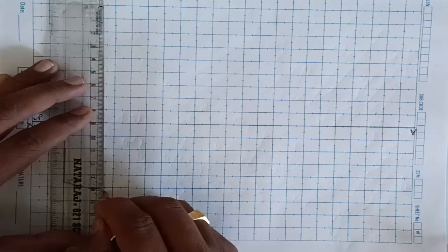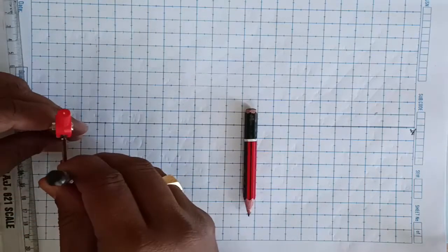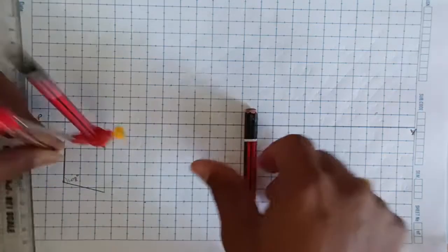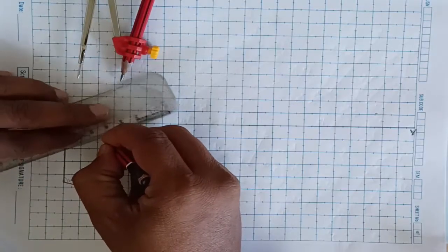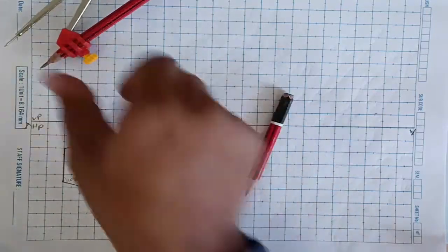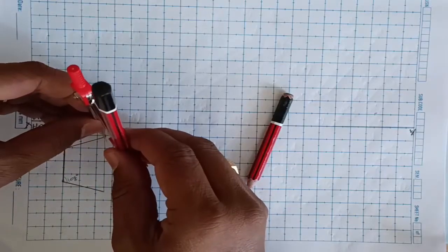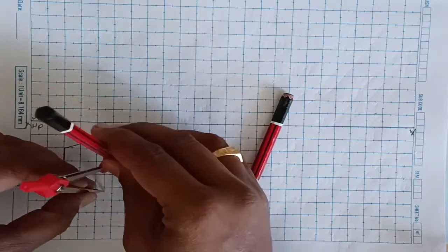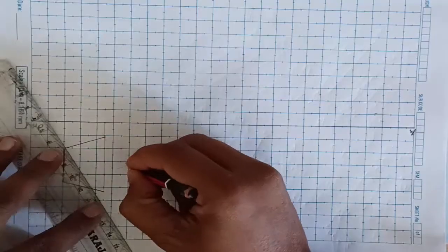From this bottom point, draw one vertical projection line and measure the same 25 mm length here. From the top point, draw an arc to the line which we drew, and from the intersection point we need to join back. This arc should be length 25. To get the fifth point, take the same 25 mm length, draw one arc from the top point and one more arc from the bottom point. Then the intersection point will be our fifth point. We can join to that.